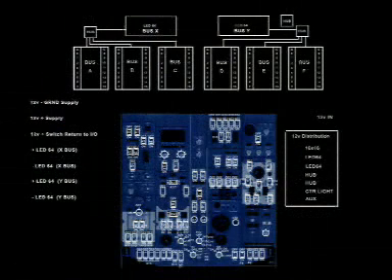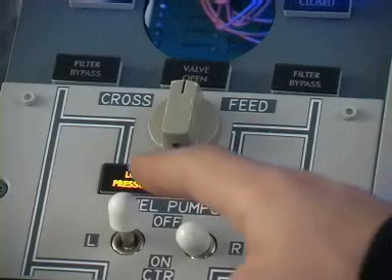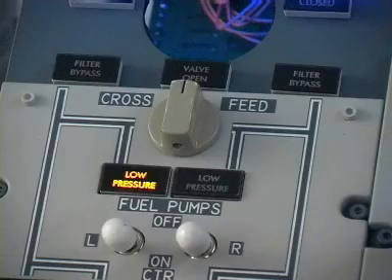These particular I/O cards required a powered input, so one side of all switches is supplied with 12 volts, and the return other side of the switch connected to the corresponding input of the card. Each card has a ground. Thus, when a switch is placed in the on position, the circuit is completed.